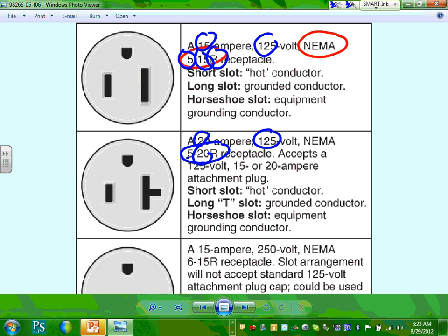Now, anybody can imagine what the plug name would be? Very easy. The plug that goes with this, the plug itself, NEMA calls it 5-20. Now, Jenny, my friend, guess. This will be R for receptacle. What would you use here for a plug? Start with a plug. P. They use the word P for a plug. That's all. So if you see 5-20P, this is actually that one here.